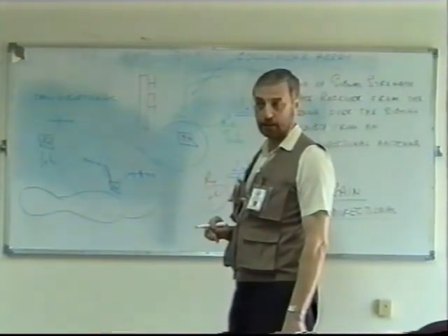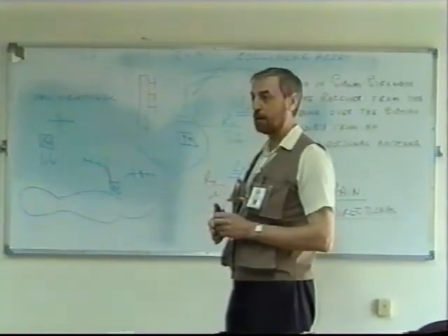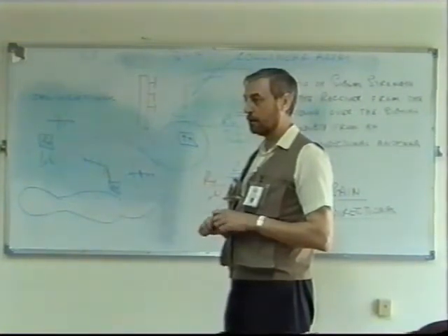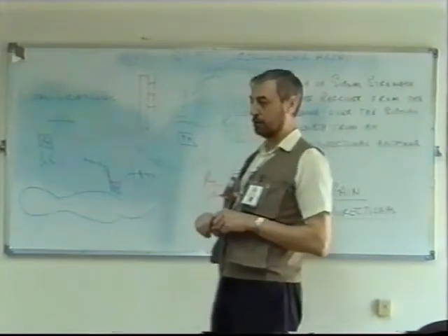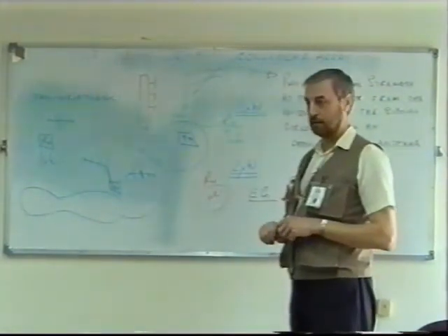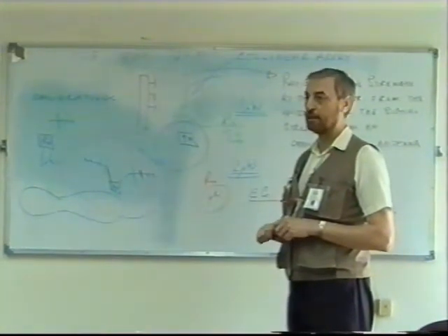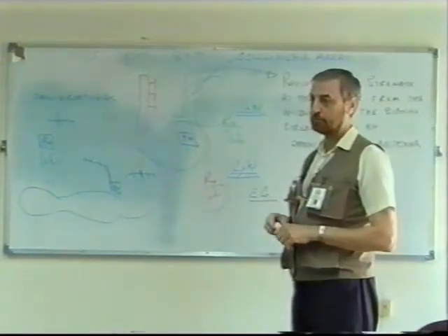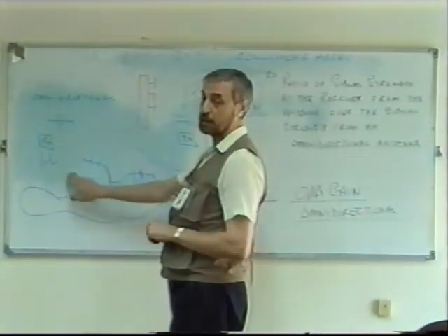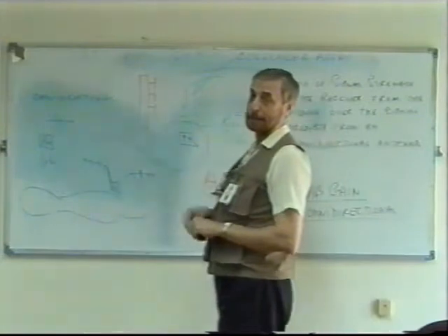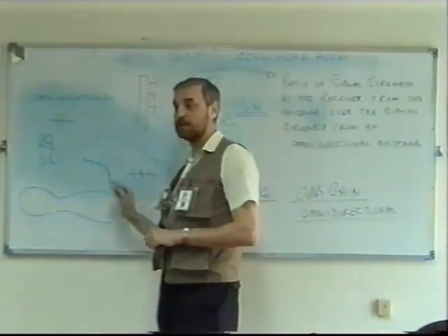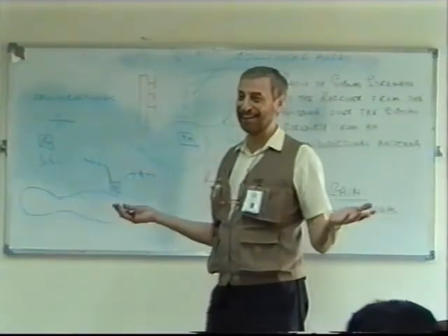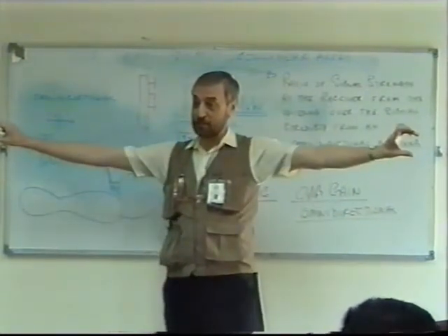Make an example that the gain may be 10 dB when I have one antenna. You mean the gain? Again, 10 dB when I have one antenna. Okay, right. When you put two antennas, it can be reduced by 3 dBs. 3 dB, not 5. This will be 7. This will be reduced by 3 dBs, and the other one also reduced. That will be the same, or should be the same. In other words, 7 dBs and 7 dBs. Yes. But you cannot just add those two together and say it's 14 dB gain. It's 7 dBs in particular directions.